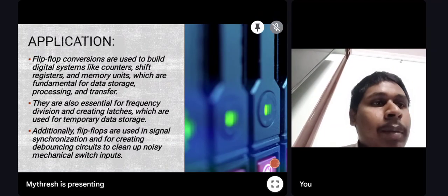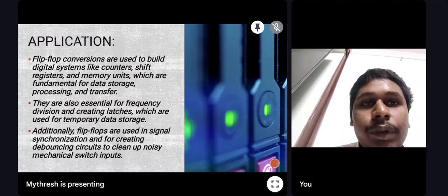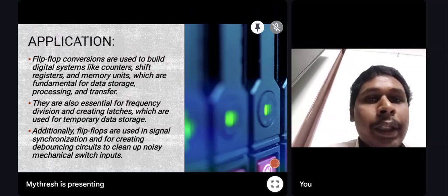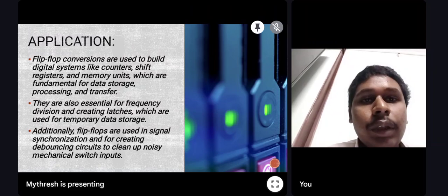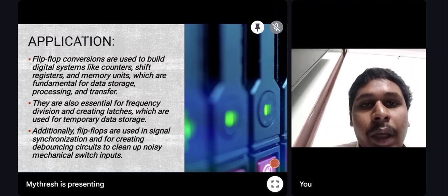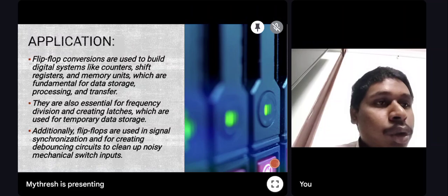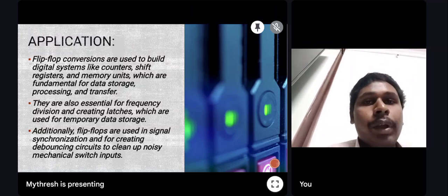So let us see some applications for the conversions. Flip-flop conversions are used to build digital systems like counters, shift registers, memory units, which are fundamental for data storage, processing and transfer. They are essential for frequency division, creating latches, which are used for temporary data. Additionally, flip-flops are used in synchronous circuits, and for creating debouncing circuits to clear noise from mechanical switch inputs. So the conversion of flip-flops is very important and can be used in daily life also.